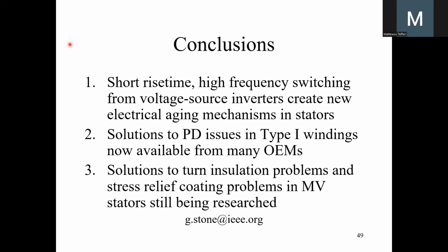All right. Another question from Jeannie. You mentioned the importance of eliminating the size of air voids between the turn insulation wires. Is it possible to completely eliminate all the voids? In my opinion, no. There's other people who may or may not disagree who might be listening, but I think you're always going to have some level of voids with the manufacturing techniques that we're using now, which is basically various kinds of impregnation.